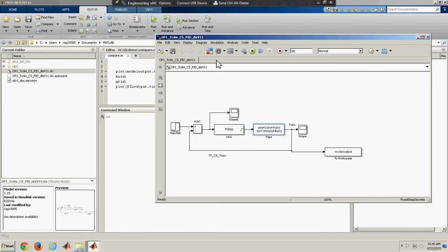And the other part is that right now we are trying to generate the autocode for this PID controller block. The name I have given for this controller block is SIL52. Whatever name I give for the controller block, if I generate the autocode for it, all the directory and file names will be based on the name of the block.